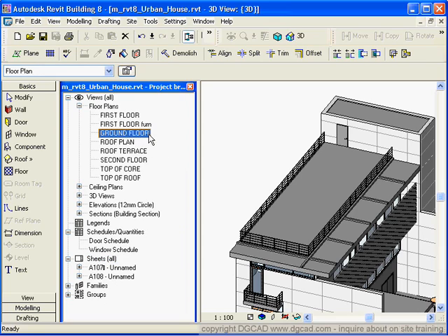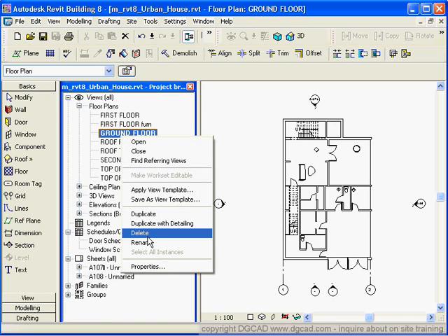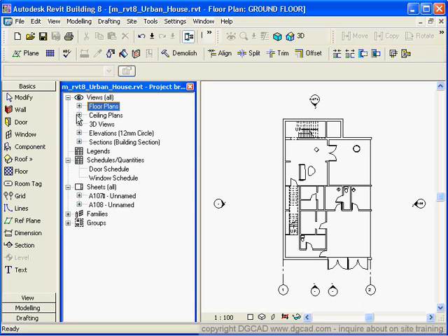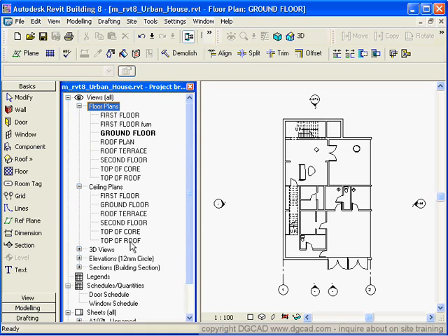It's up to you. But inside of here we can rename it, and the key is that as you're renaming all of this stuff between the drawings, they're all talking to each other. So wherever that name might show up in a drawing list, or however that field gets changed, if you change it inside of here, or you rename that or delete it, if you delete it, all the objects will delete from it, and it'll most likely give you a warning. So floor plans are view types. Every time you make a floor plan, it makes a corresponding ceiling plan for you right in there.